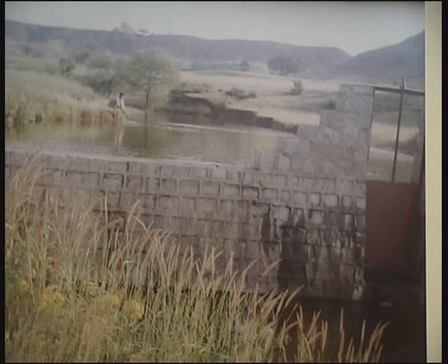In such cases, there is no need to recharge to the water table because the groundwater is already at a higher level and it is finding its way into the valley, that is, the stream course. So, in such cases where there is already a water table at very shallow depth, or the water table is almost at ground level or the bed level of the stream, there is no need for a recharge structure.